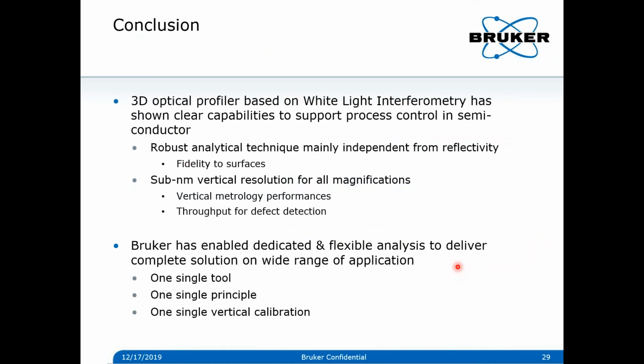So as a conclusion, as you have seen, the 3D optical profilers based on white light interferometry can definitively support process control in semiconductor environments, both front end and back end. The main core reason is that this technique is very robust, being independent from reflectivity and gaining sub-nanometer vertical resolution for all magnifications.